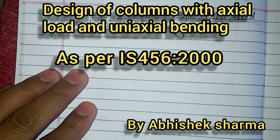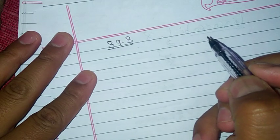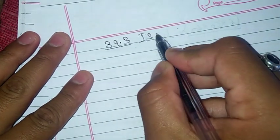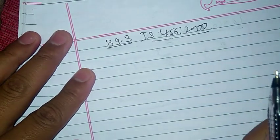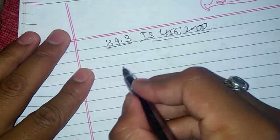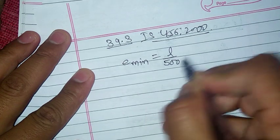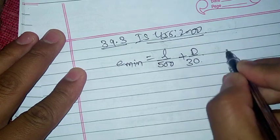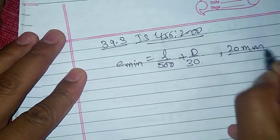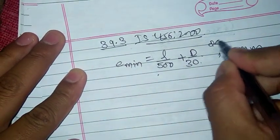As per clause 39.3 of IS 456:2000, we check the column for minimum eccentricity using the formula e minimum equals L over 500 plus D over 30, subject to a minimum of 20 mm. This formula is given in clause 25.4.